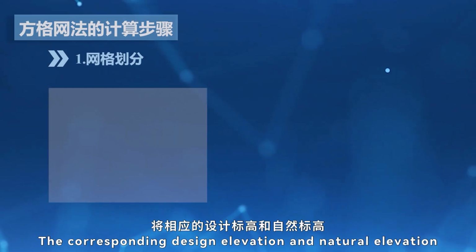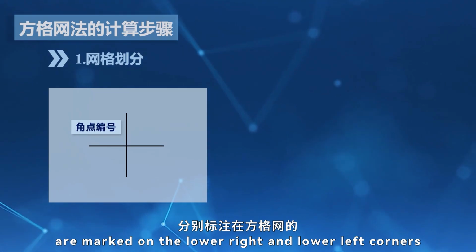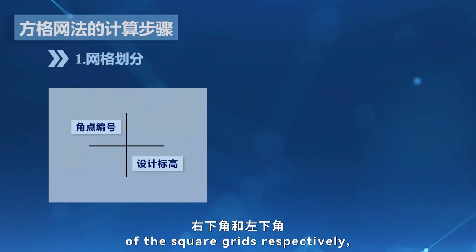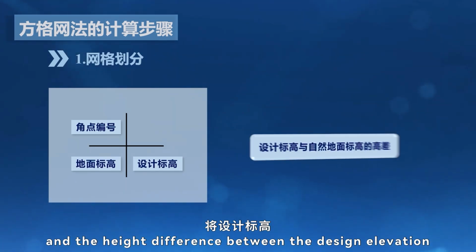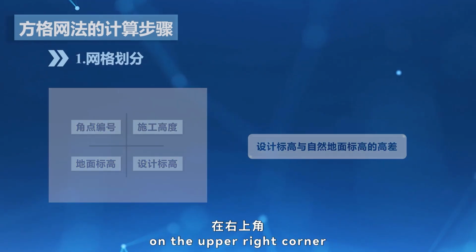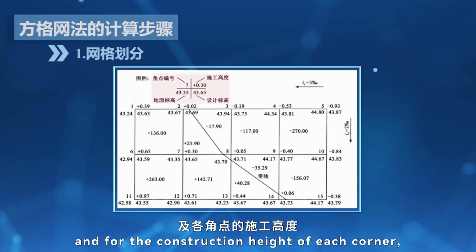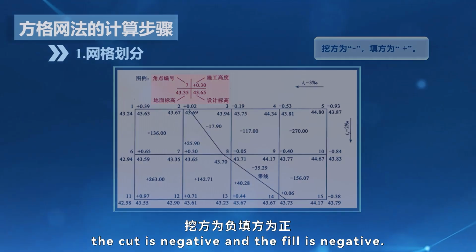The corresponding design elevation and natural elevation are marked on the lower right and the lower left corners of the square grids respectively, and the height difference between the design elevation and the natural ground elevation is marked on the upper right corner. For the construction height of each corner, the cut is negative and the fill is positive.